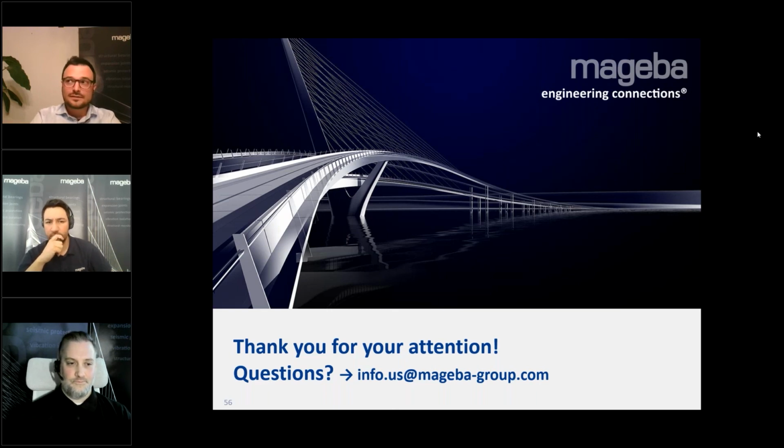In general, if the permanent loads are important, then it has to be planned carefully also with the bridge designer to follow the stage constructions and to know which stresses are taken into consideration and which stresses are lost. Yeah, for example, if half of the bridge is built and we start putting our sensors in at that time, we'd have to work with the bridge designer to ensure, okay, at the time of the sensor placement, this is what was currently constructed and what theoretical loads are being applied at that time, dead load.